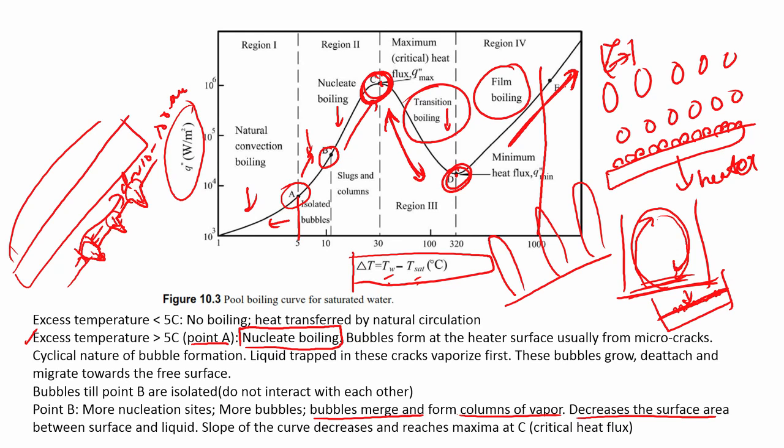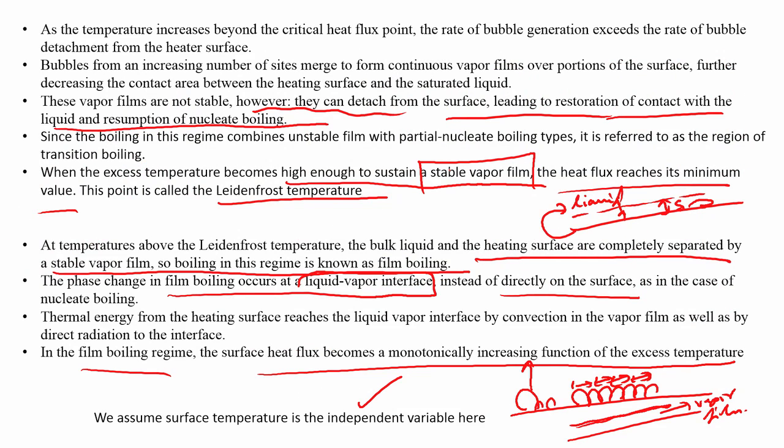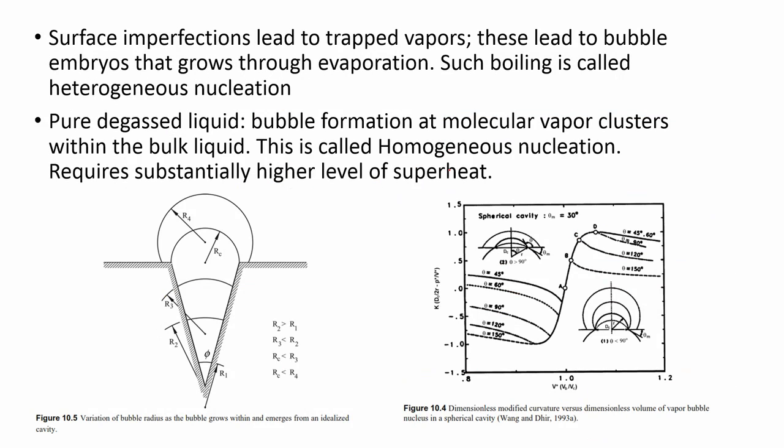heat flux, because you go to the film boiling regime, where there is a vapor that basically guards the liquid from the heated surface. So, the heat is not transferred from the surface directly to the liquid, it is actually transferred to the vapor film, and the vapor film through convection and radiation transfers the heat across the liquid vapor interface to the liquid. So, that is what happens in this particular case. So, this is the critical heat flux, this is the Leidenfrost point, and there can be the catastrophic limit at the end of the journey.